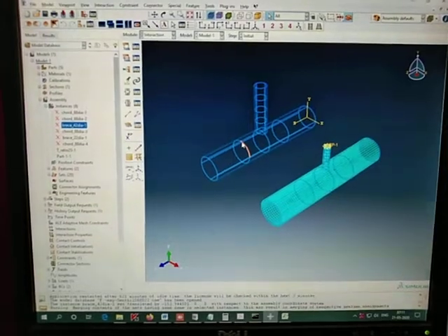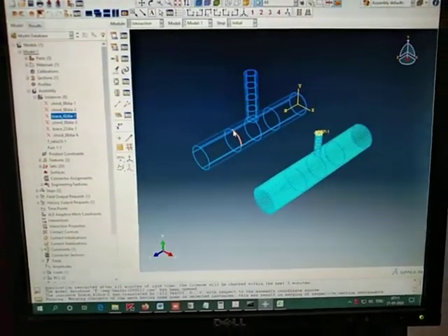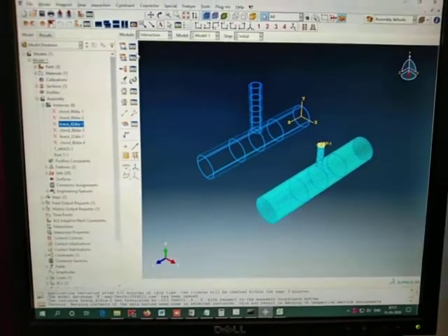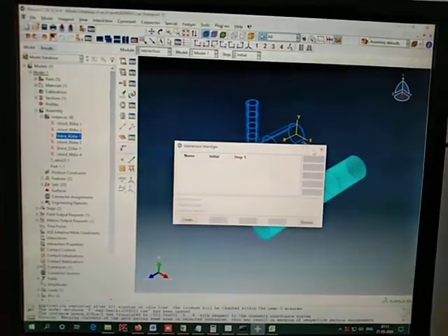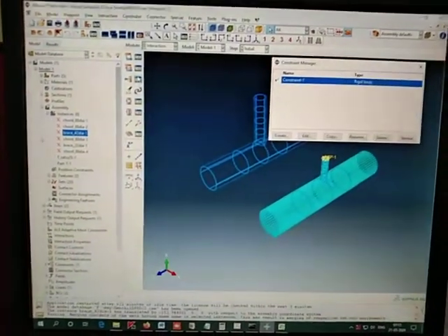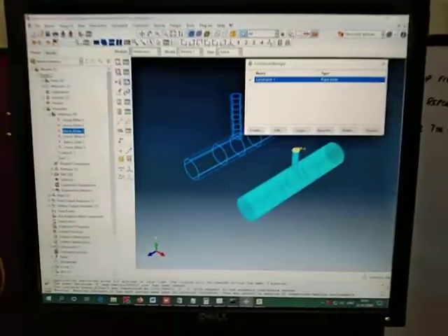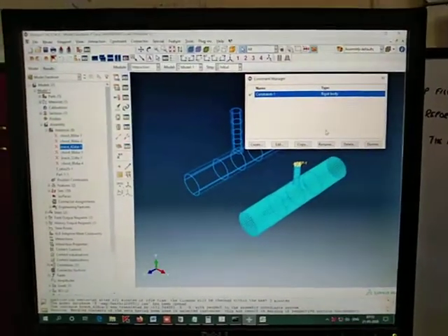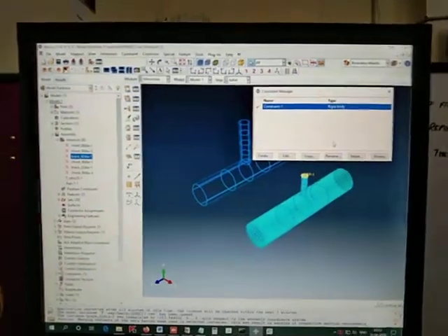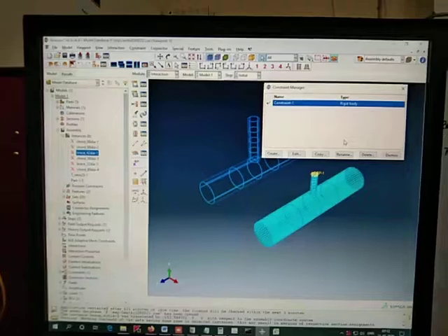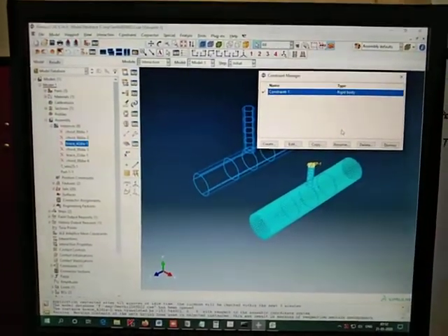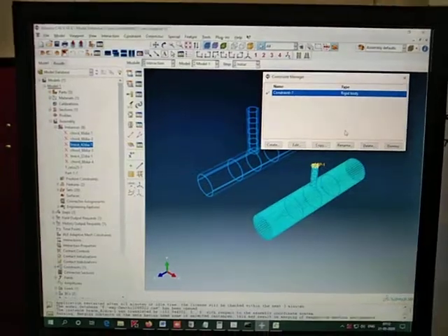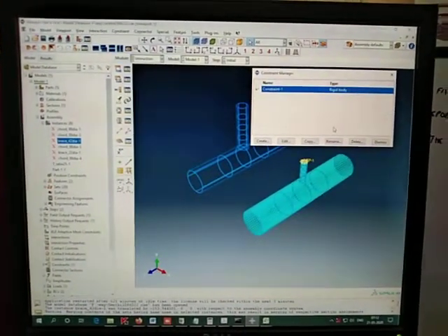Interaction. Here comes the crucial part, where we need to define how these objects will interact with each other. If there is a contact or crack, it needs to be defined here. Else we can go with the rigid body assumption. For applying load, we need to have the brace member tied up to a single point for axial load cases. Else, if it is an axial displacement, there is no need for tie constraints here. These constraints are very helpful to create the sets where, if you are giving stiffness or any other thing, the output is required. These constraints will help you take the output earlier, rather than going and selecting the specific surfaces at the later stage of post processing. It is better to define those constraints or sets here.